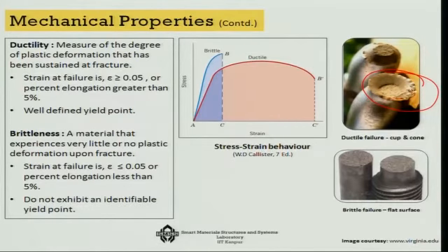So, the difference between a brittle and a ductile system, I have already drawn the stress strain curve for a brittle system, and a ductile system, is precisely the presence of this plastic strain that is there for a ductile material, and that is absent for a brittle material. So, that is a very important point that we have to keep in our mind while comparing various material properties.